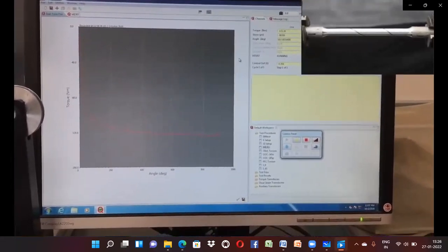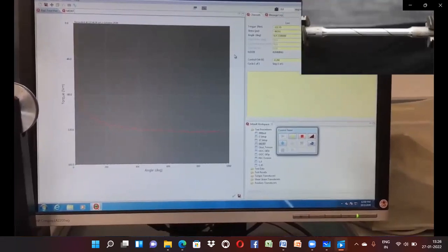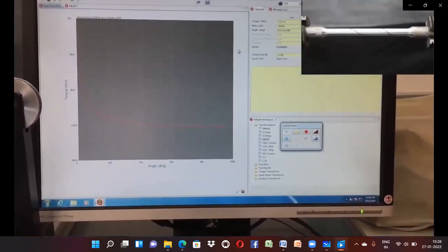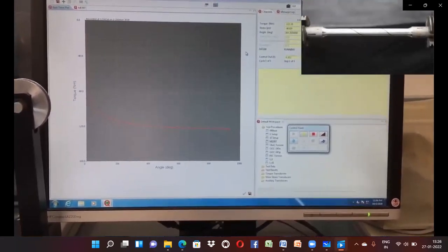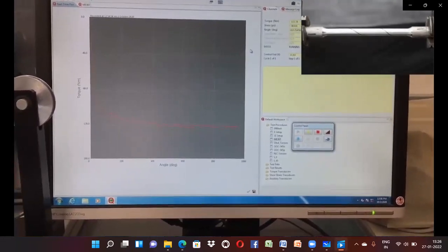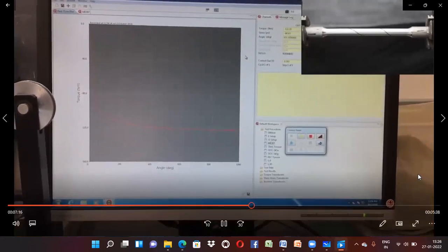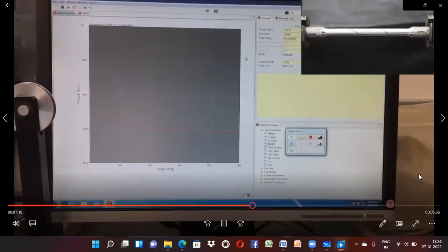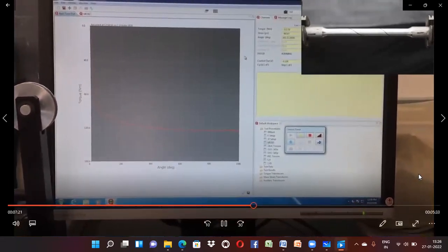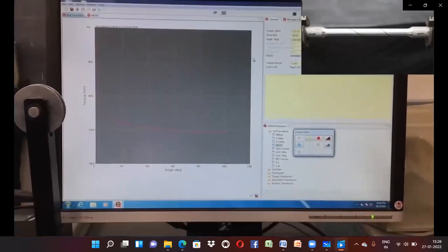We won't be doing it because you guys don't quite have the information you need from 303 or 306. But the first place to identify yielding is when it becomes nonlinear at about, it looks like maybe about 30 or 50 degrees of twist there. The other way to do it is by looking at once it's all yielding, what is its maximum sustained torque.